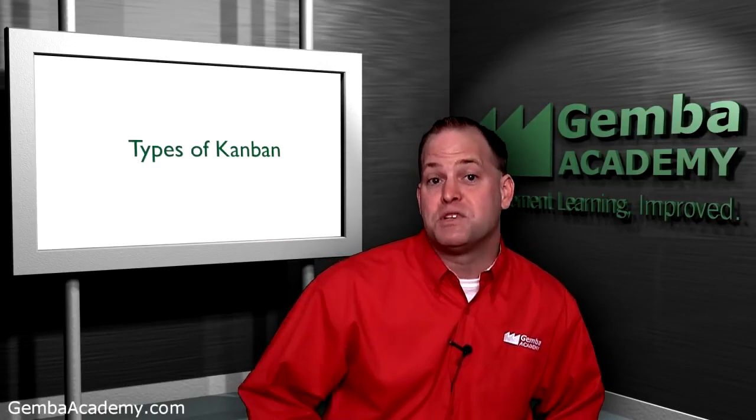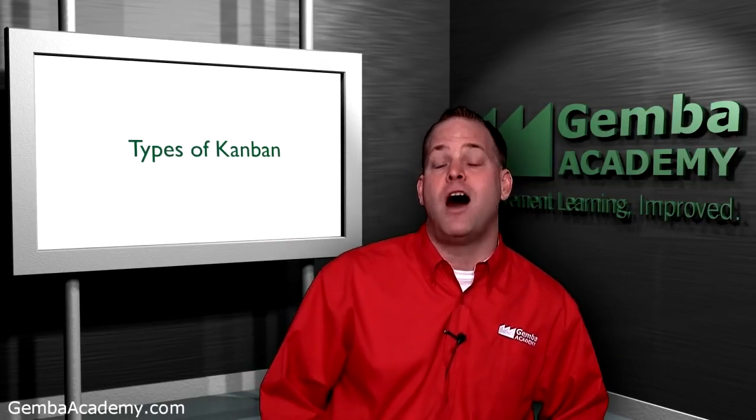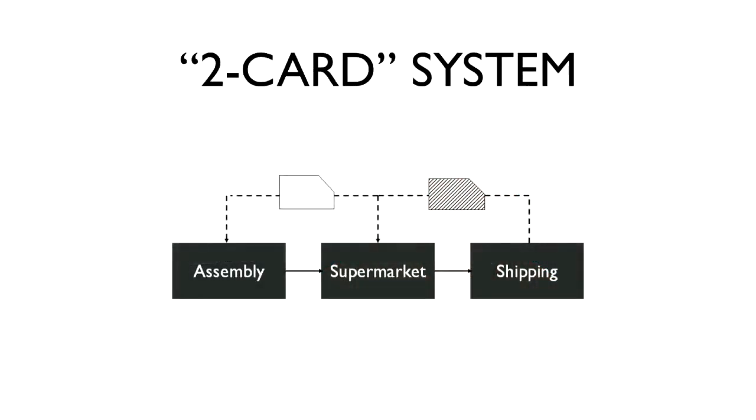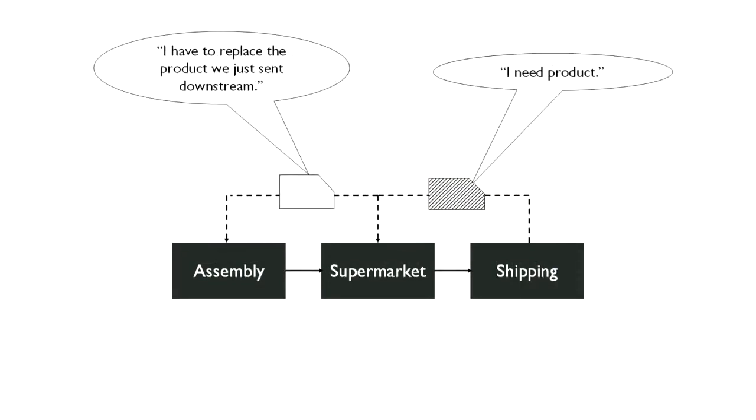Alright, well, to wrap up this first overview module, let's learn about some of the most common types of Kanban. Well, the first type of Kanban is the classic two-card system, where production and withdrawal Kanban cards are used. In this example, we see a shaded withdrawal Kanban going from shipping to the supermarket. Now, this is a signal from shipping to the supermarket that it needs product to meet a customer request. Once a shipping clerk removes product from the supermarket, a production Kanban will be sent to the assembly department, signaling there's an item missing in the supermarket that needs to be replenished.